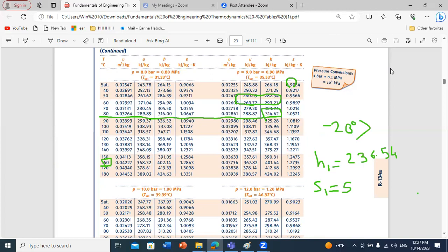Here, if they gave us the temperature at the outlet of the compressor, do we consider it as isentropic? Because you wrote down S1 is equal to S2, right? No. Because if they give you the temperature, there will be a contradiction. For example, if they tell you the outlet temperature is 50 degrees, while at 8 bars, in case S is constant, the temperature will be different. So if I impose the temperature, then you cannot say I will model it as isentropic. There might be some irreversibilities.